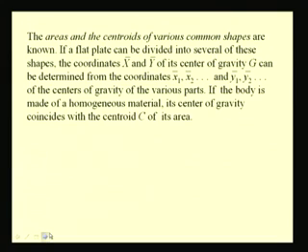So, let us see this. The areas and centroids of various shapes are known. So, if a flat plate can be divided into several of these shapes, then the coordinates x bar and y bar of the center of gravity can be determined from the coordinates, that is x1 bar, x2 bar, etc. of these various parts.